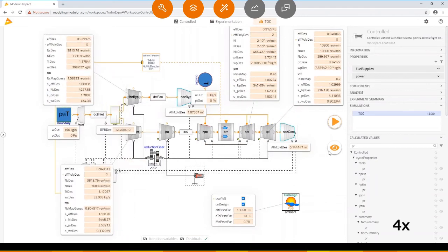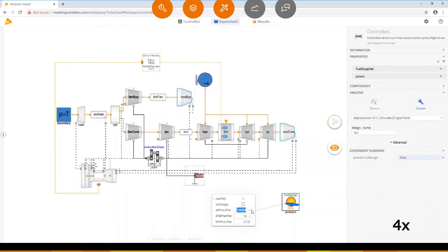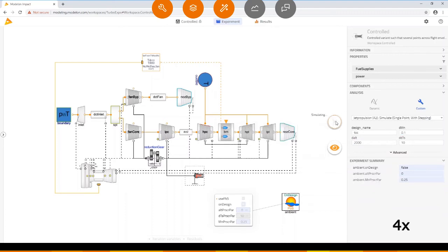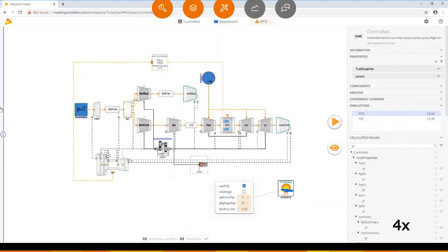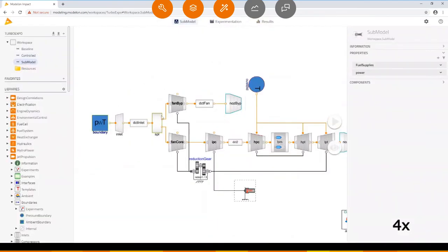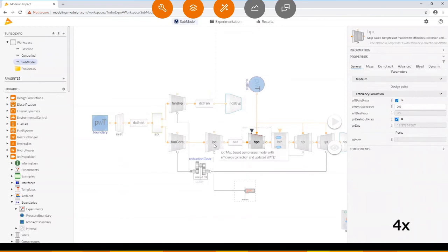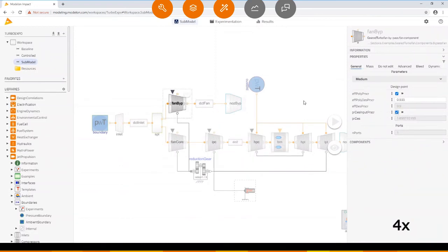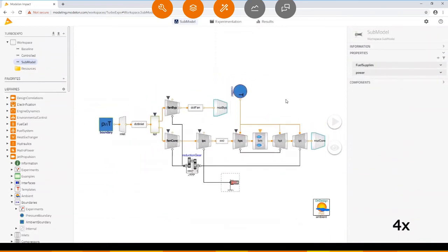Then an off-design simulation is run by stepping the boundary conditions from a known solution to the ones of interest. Here, the Mach number, for instance, is changed at most by 0.1 increments. The results are named RTO for rolling takeoff. A second submodel is extended from the baseline plant model and configured again for external control, this time for both operation in orange and sizing in blue.